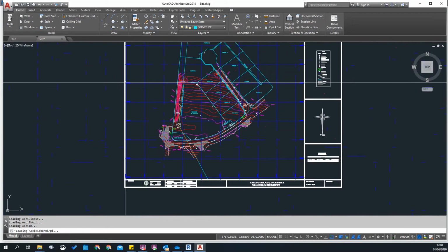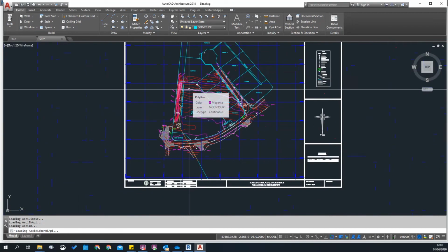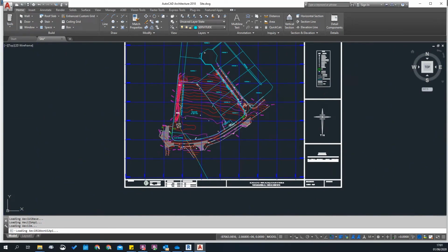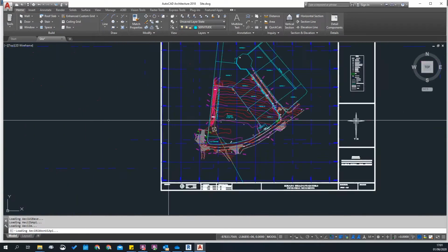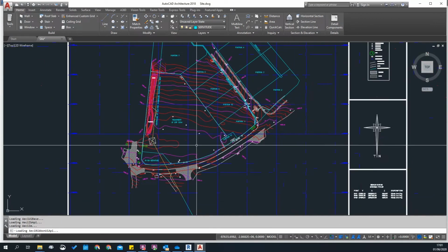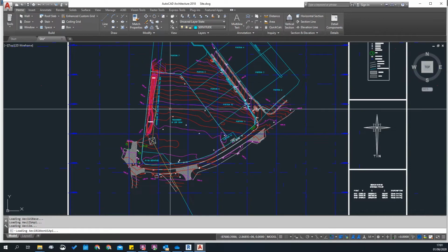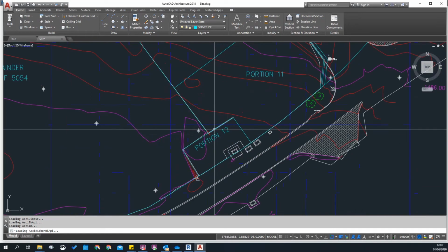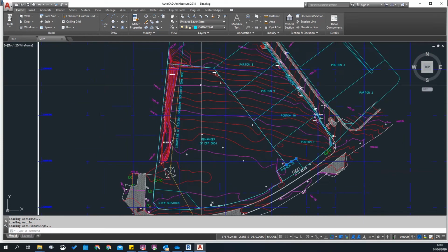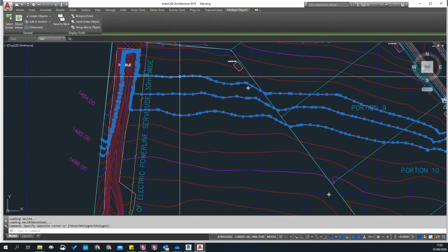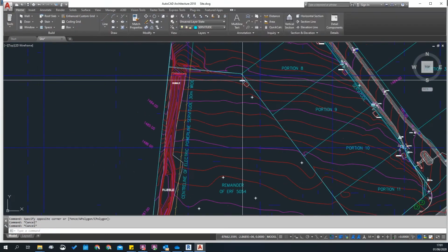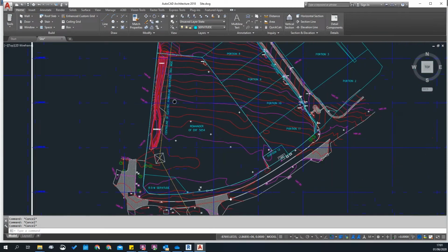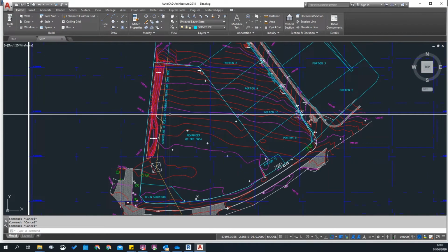He's going to give you the site boundaries, and of course the contours, which is very important. So for this exercise, initially all you want to do is gather all the site information, the cadastral information, and you want to gather the topography, because the topography is what you're going to use to then model your 3D topography in Revit, and this is a great place to start.